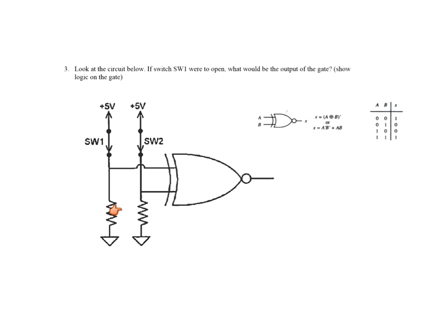Okay, now let's take a look at this. Sometimes you'll see it like this. Let me draw it for you. Up here you have a positive 5. And over here on the top, sometimes you'll see a resistor, sometimes you won't. And then there's a switch right here. That's what SW1 means. And down here is a resistor going to ground.